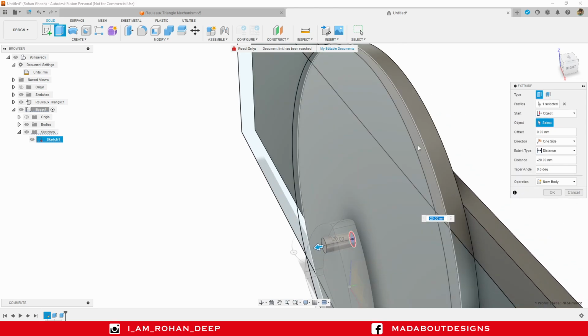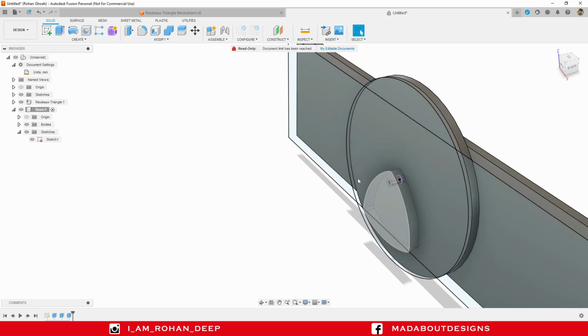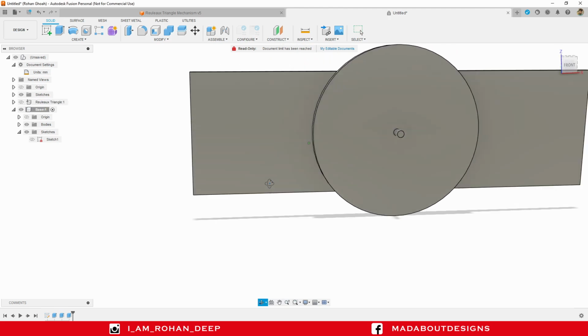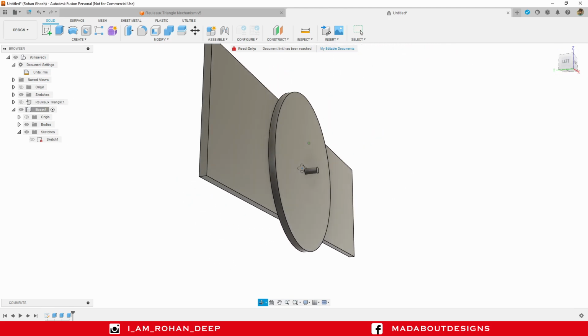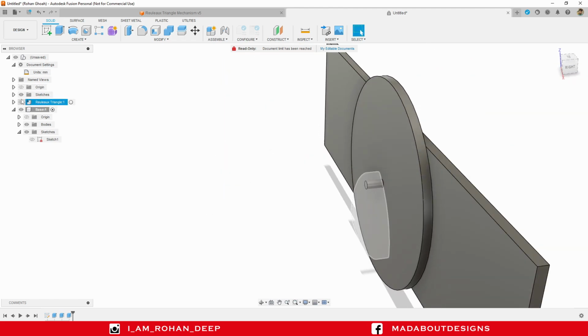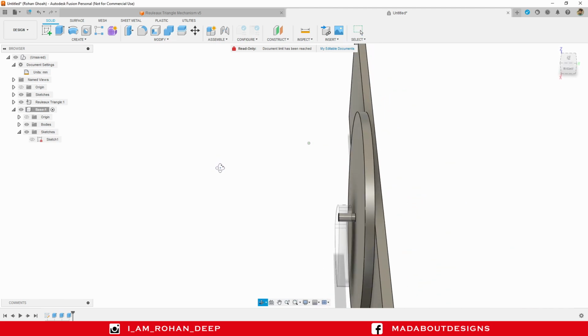Select this surface of the circular disc. Operation Join. Click OK. Hide the sketch one and the Reuleaux triangle. Here is our base ready. If I turn on the visibility, you can see the complete assembly.